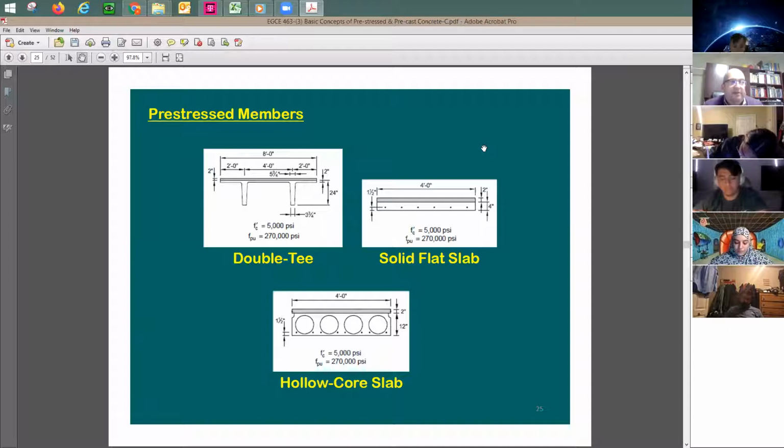Developing the form and the cost of putting the form all together is going to be very expensive. This form is used hundreds of times, and they keep on using it. And as you see here, they paint it with some oil, they call it form release, and then after that, they strip the double T, they just pull it up, and then they repeat the process. So don't go to a weird size or your own size. Stay with the standard size.